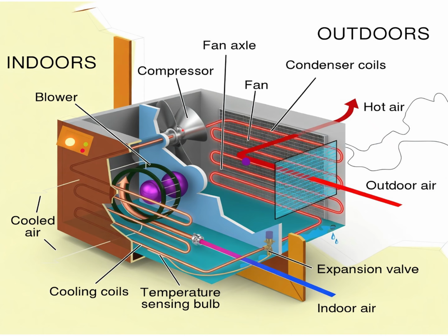So from compressor, the gas will come in that direction. So this is the inner side. You can see the wall. Here is the wall. This is the inner side which contains the cooling coil, because the main function of the AC is to cool. Then this is the outer side. In our rooftop, you sometimes see some fan. So this is actually the condenser fan. This is the condenser which is kept outside of your room.